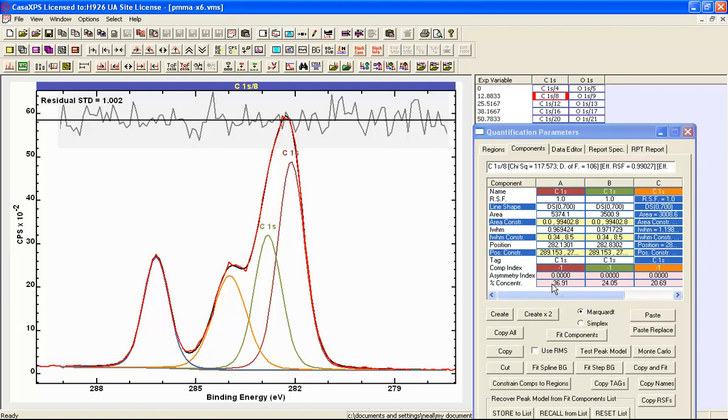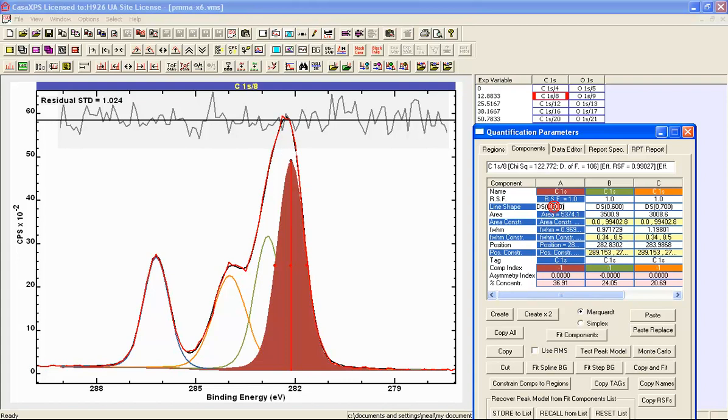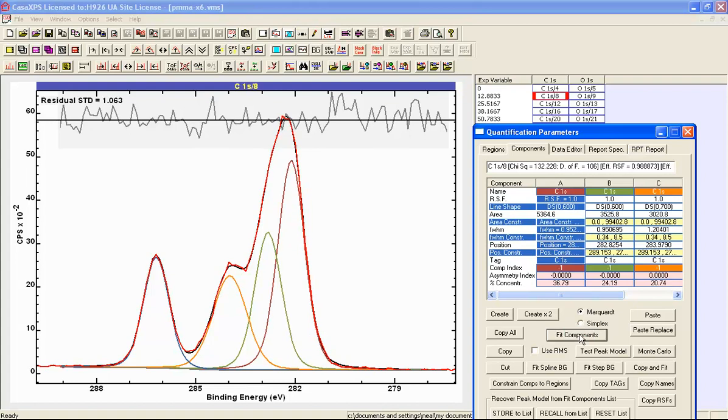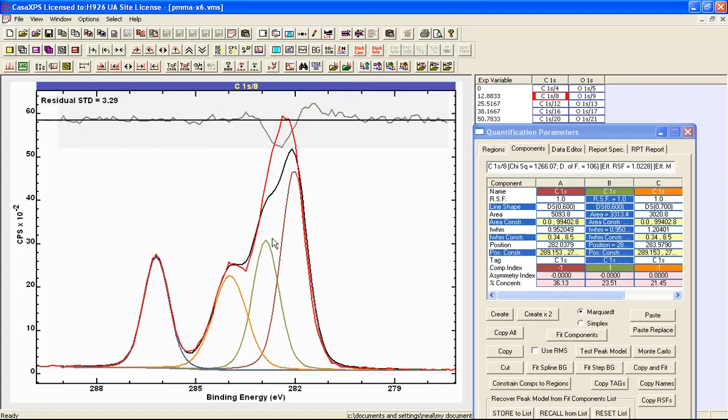but we still need to be sure that the peaks themselves are looking like the ratios we would expect for polymethyl methacrylate, and in this case we can see that we're losing some of the relationships. So the ratio of these two peaks should be 2-to-1, and they're moving apart by virtue of these adjustments I've just made. So let's adjust the line shapes, and we'll make the CC peak more Lorentzian, and perhaps we'll do the same for the CH peak, and then we'll say fit, and perhaps we need to give this a little bit of help in terms of